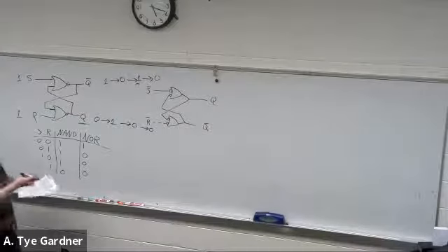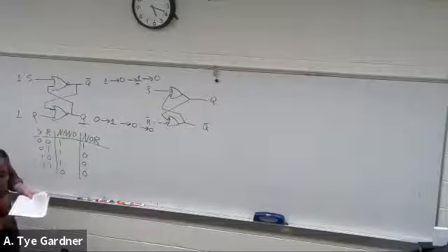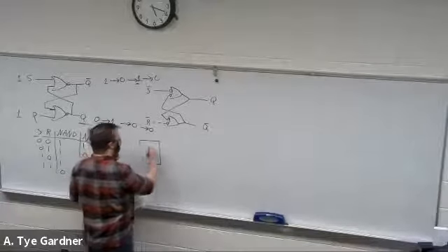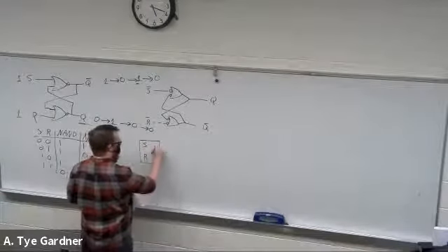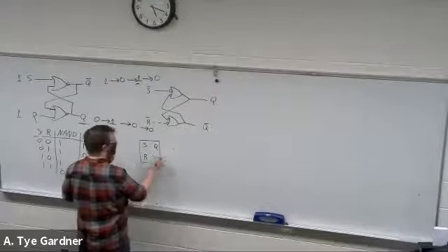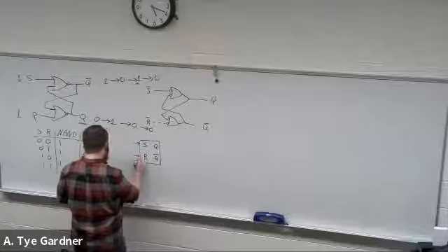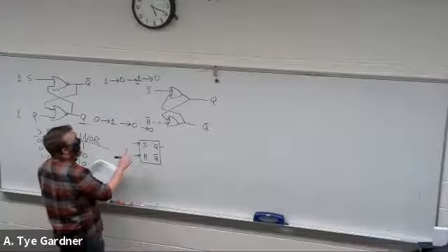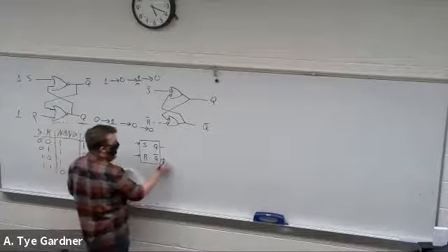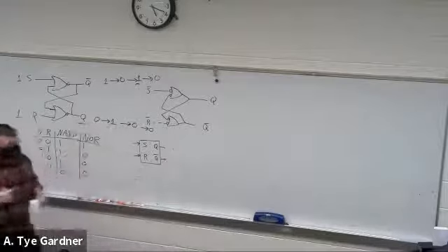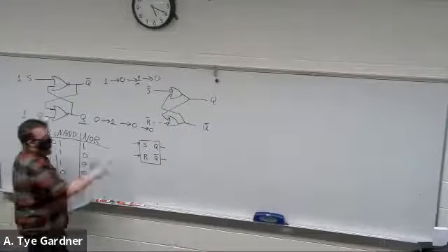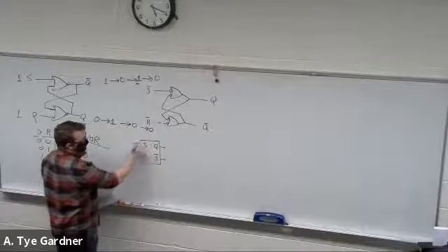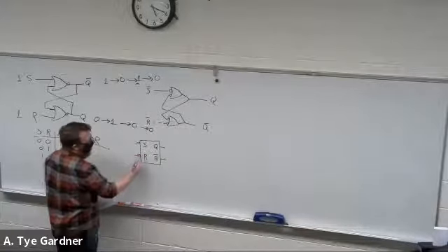When we make this, we don't want to draw this circuit all the time because it would be annoying. So much like everything else, we make a schematic symbol for it. It's going to have set, reset, and Q and Q bar. The definition of this matters, right? So this is saying active high sets. If I wanted to use this circuit with active low inputs, I would just put bubbles at the input, which means they're active low.